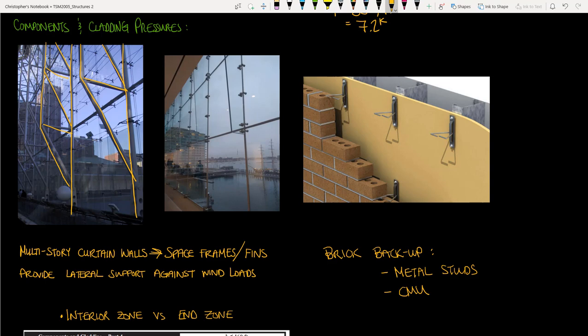Beyond this cavity, there is also a weather barrier, insulation, and possibly other architectural envelope layers. And behind all of this, we have our stud wall. And this stud wall is what we hang our gypsum board or other interior finishes on, and it is also what provides the additional stiffness we need to support the brick laterally.